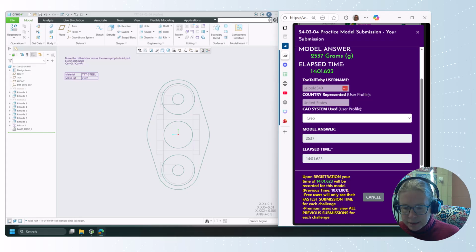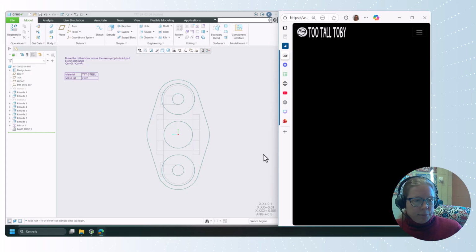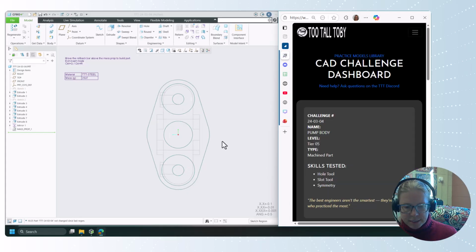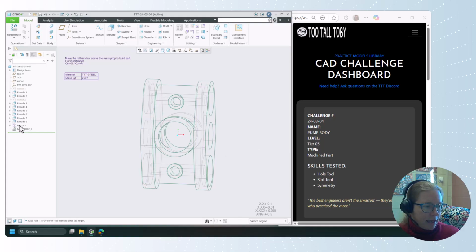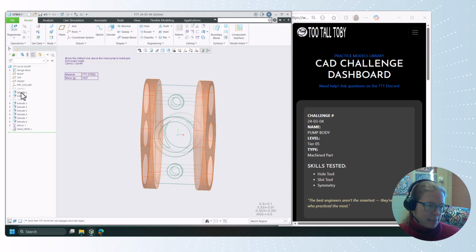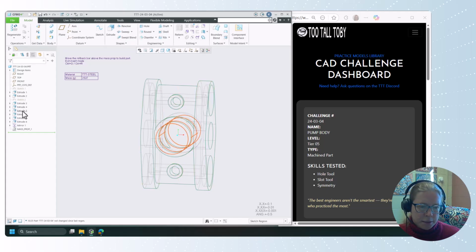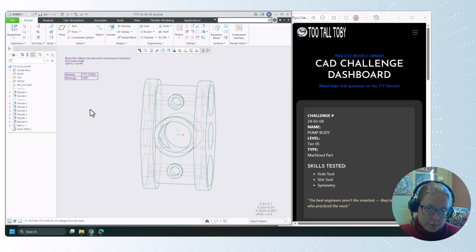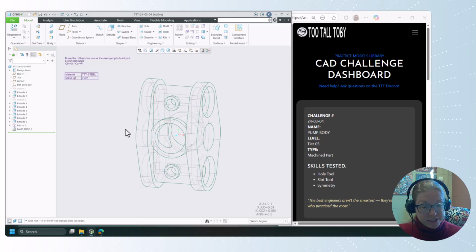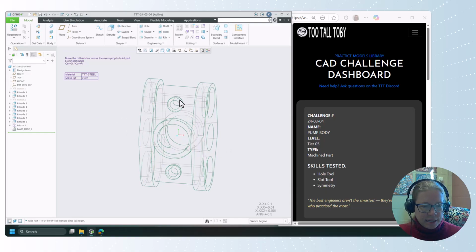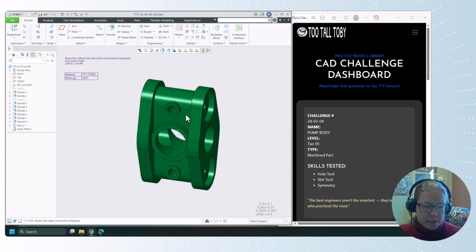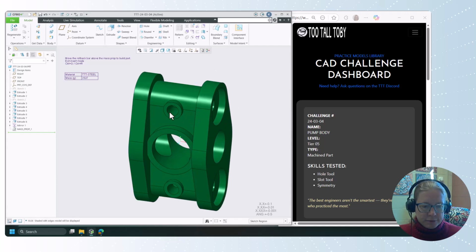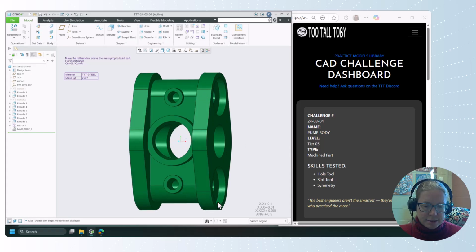So a couple of things happening here. I definitely took advantage of sketch region. There's a lot of extrudes in this one. It'd be a really good idea to go in and give these some meaningful names. I also found, I've done this more than once, that adding these bump outs, it is definitely helpful to make these side cuts last.